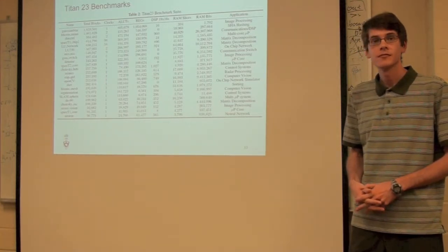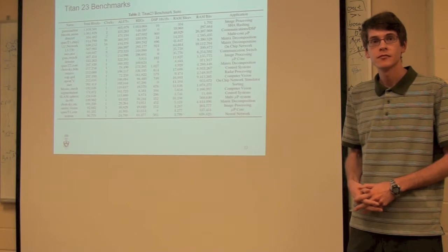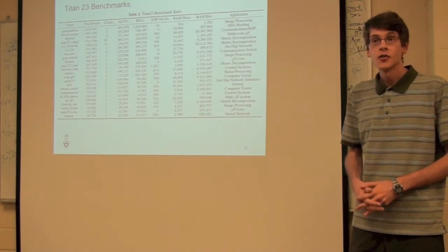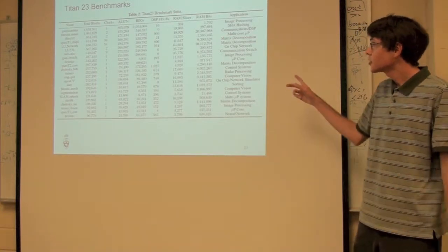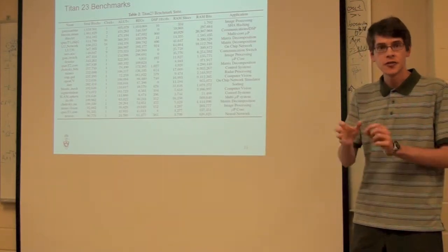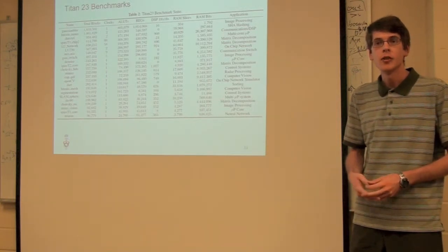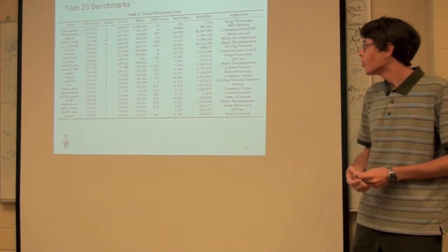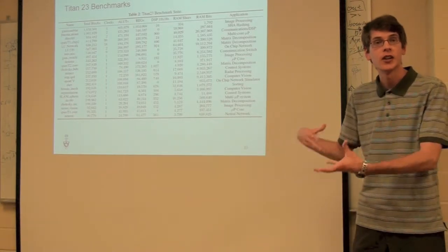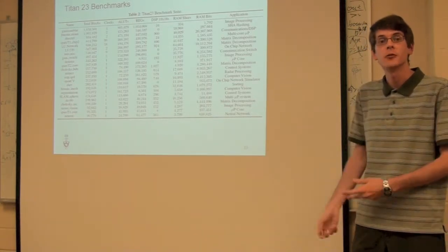In your release, you're releasing an architecture file as well? Yes. And what version of VPR are you using, actually? These results were on an early version of 7. If you look at the paper, it says the exact revision number that we used. We're working basically off the trunk at this point because it has features like carry chains that we want to have in for the timing-driven portion of it.